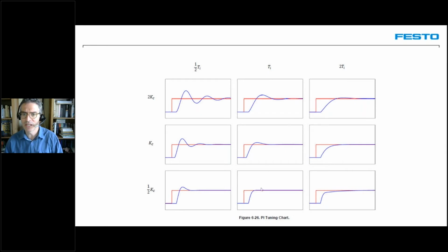If we divide the gain, then we will cut the overshoot, but as you can see, the increase will be slower. On the opposite, if we play with the I parameter, leaving the gain the same and multiplying by 2 the TI parameter, so decreasing the impact of the TI parameter by 2, you can see that it will respond slower.